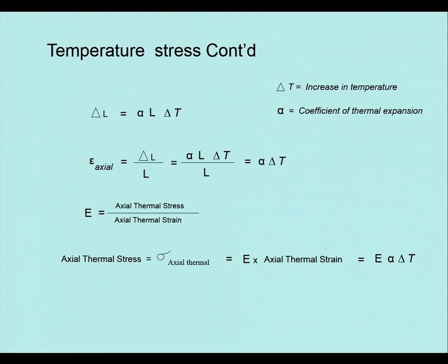So, what's that telling you? We're using the modulus of the material to get the stress. Assuming it's remaining in the elastic zone at all times. But more importantly, it's not a function of length. Length gone.